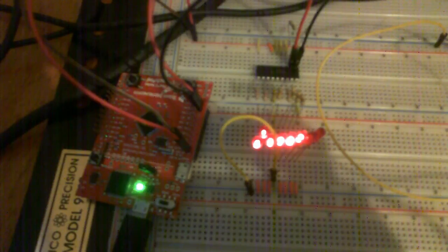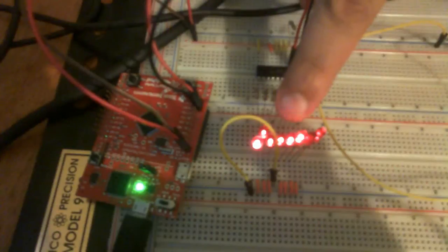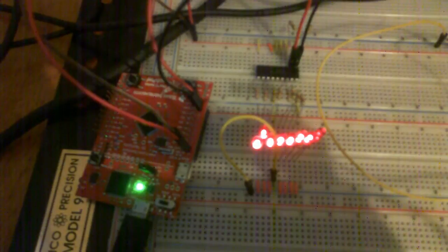In my SPI video, I show you how to use the SPI peripheral on your microcontroller to drive 8 LEDs. In this tutorial, I will show you how to do the same thing but using I2C. So what I have done is I have bought the IO expander I2C version. Last time we were using the SPI version. So I'm controlling these 8 LEDs using only the 2 pins that the I2C protocol requires. So let's go check out the code.